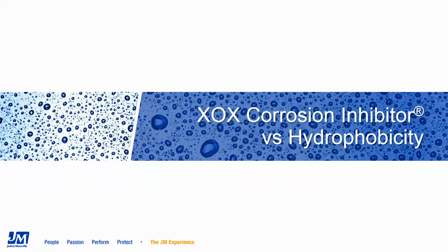So another thing to consider for strategies in CUI is utilizing insulations that have integral corrosion inhibitors. Keep in mind, corrosion inhibitors are not the same as hydrophobic substances, and I'll let Marybeth elaborate more on it. Thanks, Matt. So far, we've talked a lot about water as it relates to the insulation's physical properties. But what does that really mean when it comes to CUI? We know that water is an integral part of the corrosion triangle, but is it really the most important piece? And how does that compare to the material properties, including corrosion inhibitors, when it comes to CUI?